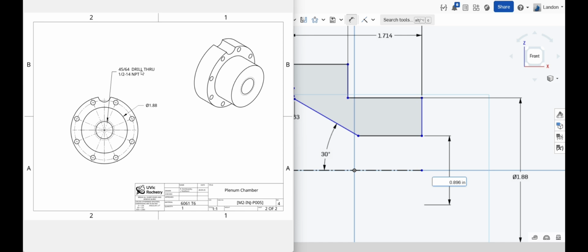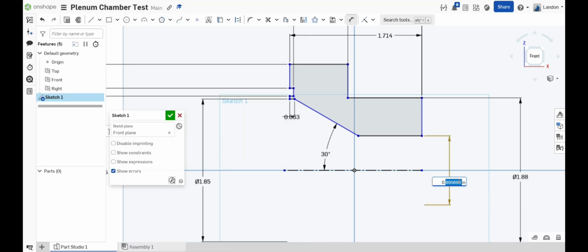That makes sense to make this a 45/64 drill. But if we do it like that, and then we use the hole feature in Onshape to tap it, it will be undefined. Therefore, let's just make it 1/2 of an inch so it has material to take away.